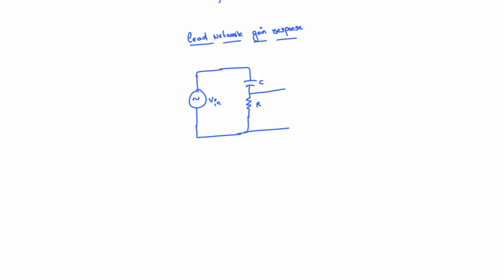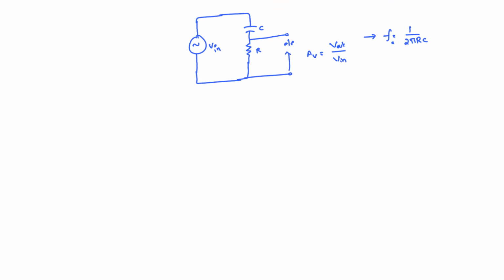I want to take the output at the resistor R. One important thing you can observe: the gain of this system is generally output by input. When you put that gain in terms of decibels, you generally write 10 log of gain to the base 10, but that is applicable only when you draw the gain for power. When you draw the gain for voltage, it should be multiplied by 2, because power is directly proportional to the square of the voltage. So the gain becomes 20 log G to the base 10.